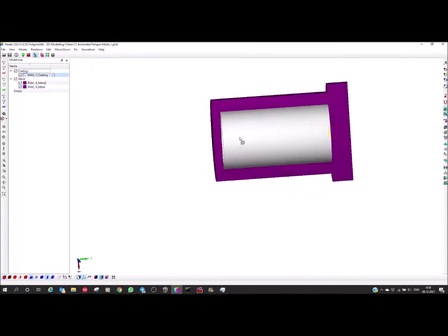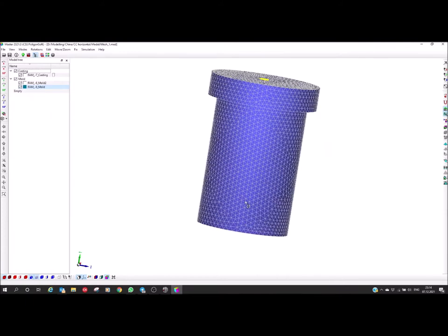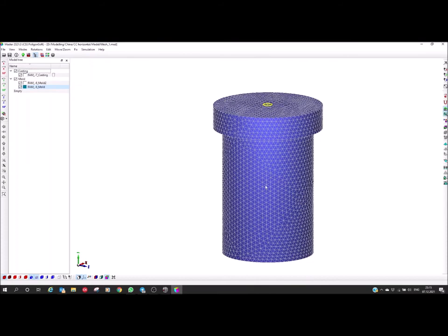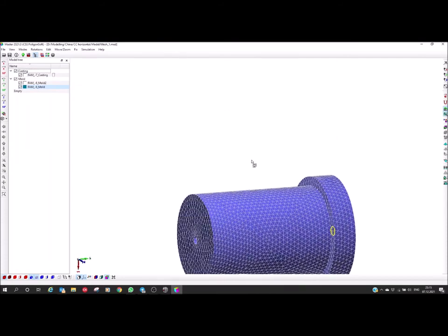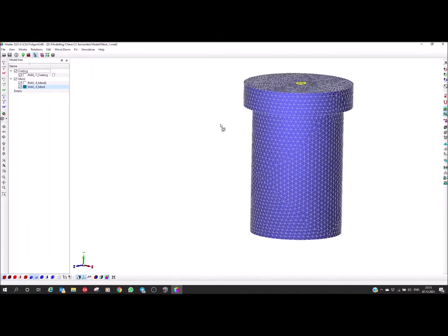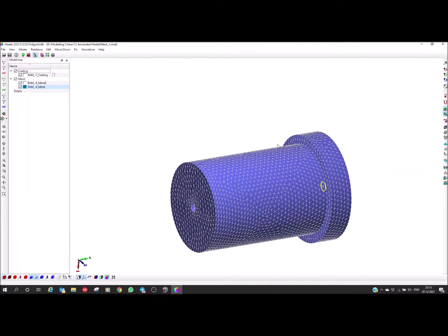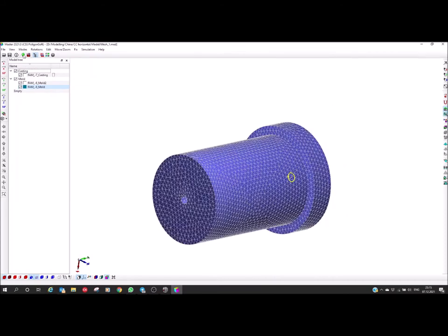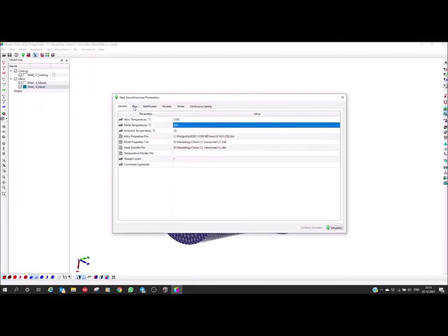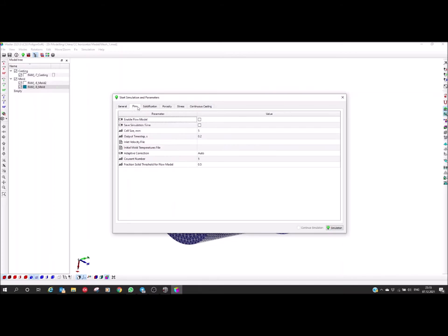I have a steel mold and iron casting. So as we use in PoligonSoft gravity vector direction against the Y axis, but in our case in horizontal centrifugal casting, the right position of the geometry is not like this, but like this. So we can't simulate filling, but we can simulate solidification, and we can simulate stress, and I will show how to do it. Go to the Start Simulation Parameters window, and on the Flow tab, this parameter Enable Flow Model must be switched off.